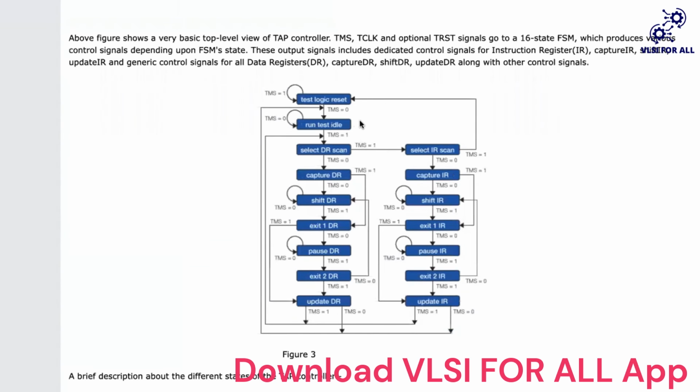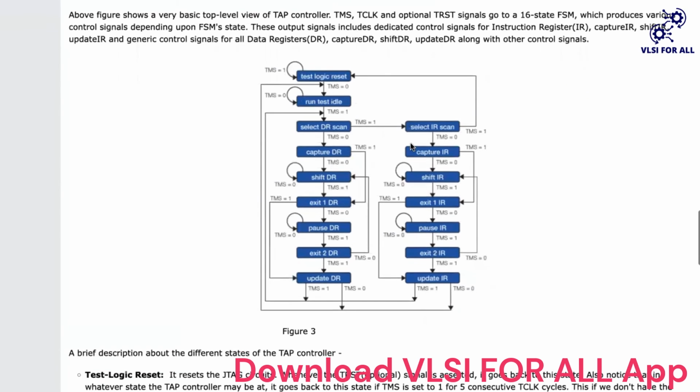Okay, what you need to focus mostly on is this: what is this DR, what is this IR, and these three states: capture, shift, and update. These three states you need to understand, and you need to understand this test reset logic. These 4 or 5 things, if you understand, I think it should be good enough for every electronics interview or anything which asks for the TAP controller. If you answer these questions, I think that should be enough.